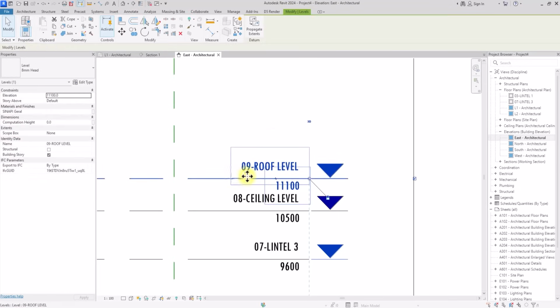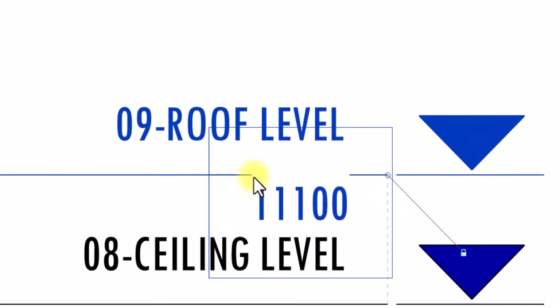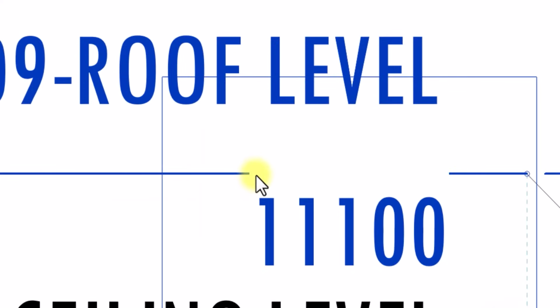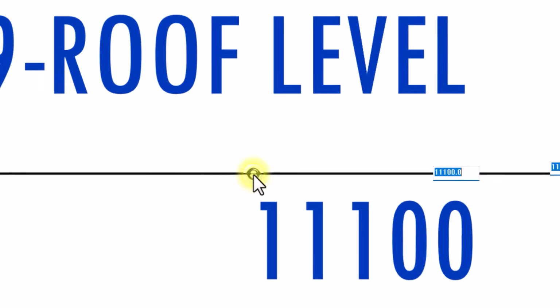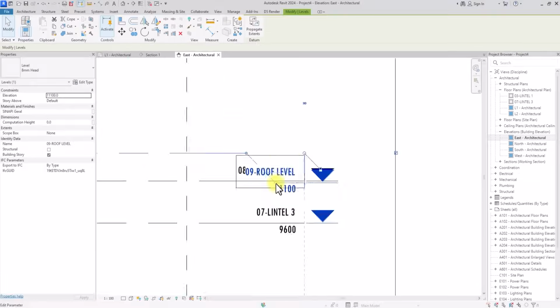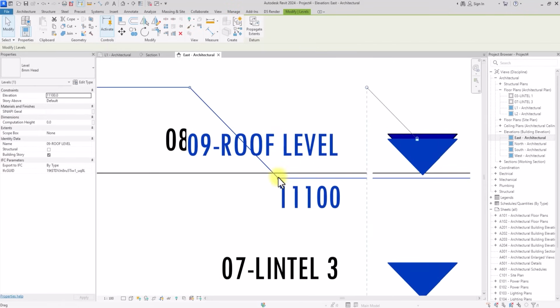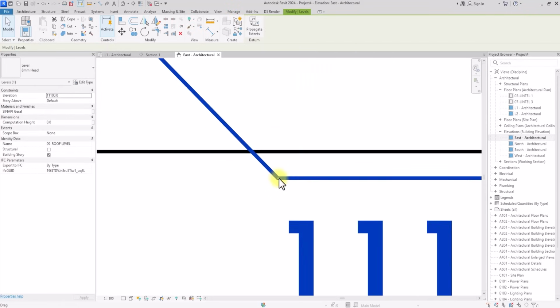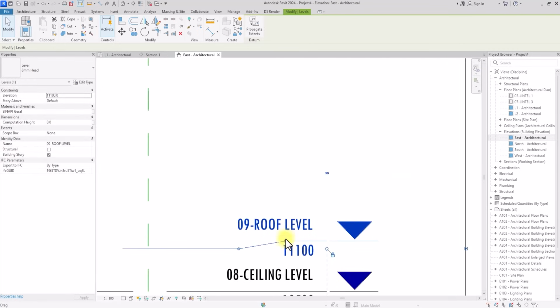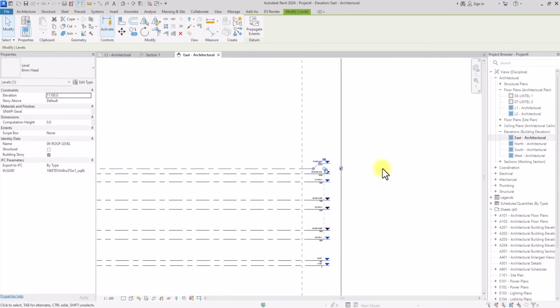So now I'm just going to click on this level. I'm going to click on this zigzag icon in between to displace it. I'm going to zoom in and click on it. So now I've clicked on it, it will displace the level annotation. So I could just click on this circle here, zoom in, click on this circle and adjust it, so I'll be able to adjust it appropriately so it will not be interfering.